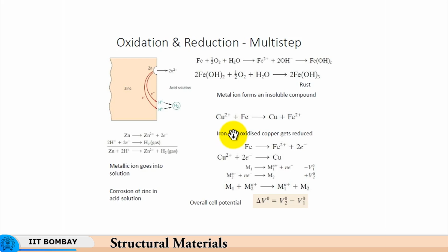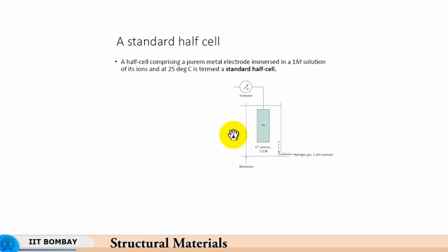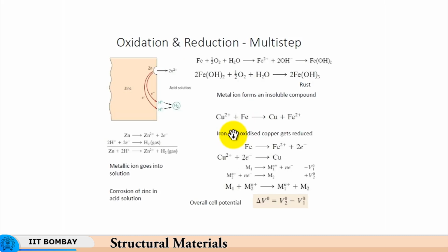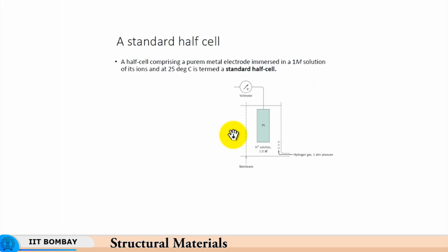So, just the presence of iron and oxygen is not going to make any difference, it is not going to result in rusting, but here presence of moisture causes all the damage. So, we have seen all this earlier, and so we come to the concept of a half cell, where you generate a potential or some kind of voltage as a result of this ionization taking place, the oxidation or reduction reaction that is taking place.